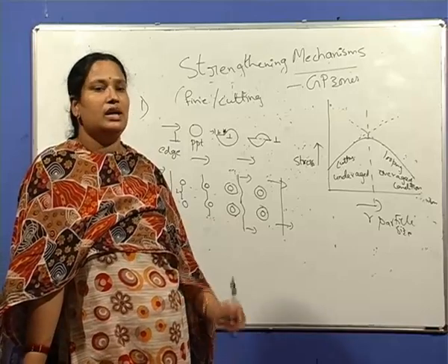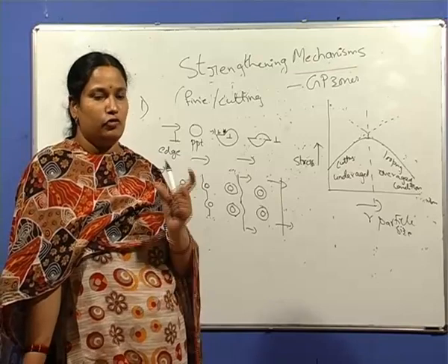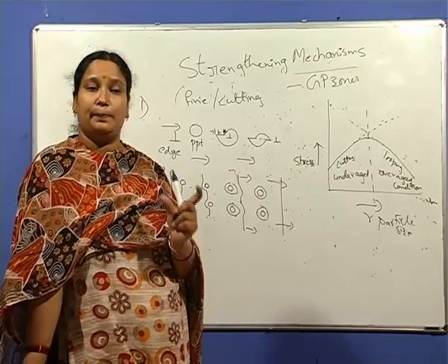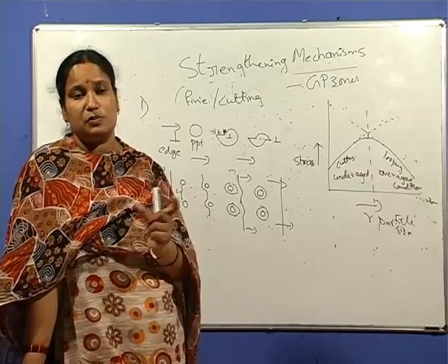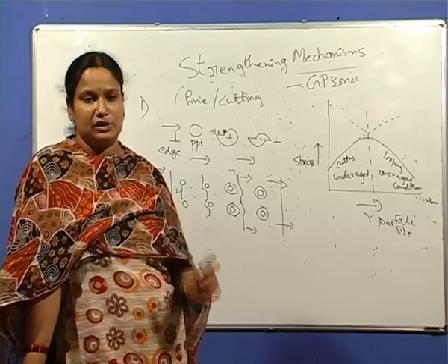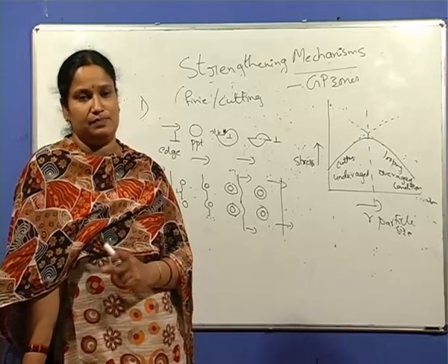Moreover, in any precipitation hardening system, the main phases are the formation of a coherent precipitate phase, where the peak hardness is achieved, and then a coarse precipitate, which is not coherent with the matrix phase, forms at higher or longer aging times.